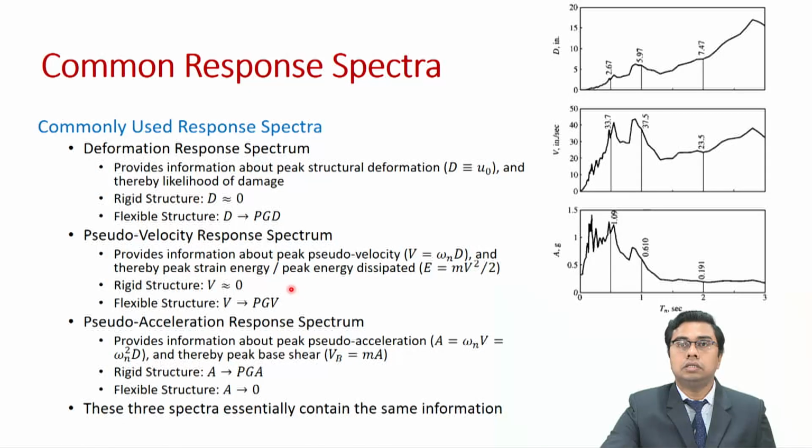For rigid structures, the pseudo velocity response spectrum has a value of 0. For flexible structures, that is structures with large natural periods, the pseudo velocity response spectrum approaches peak ground velocity.